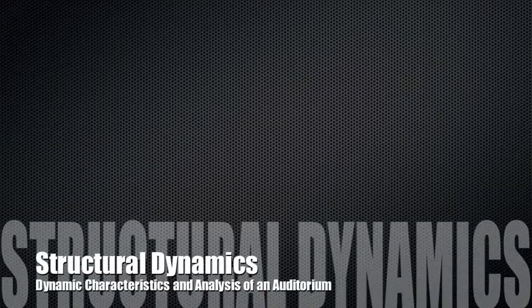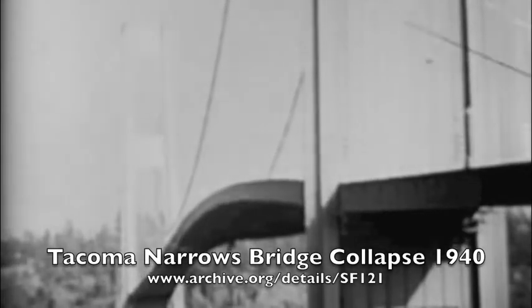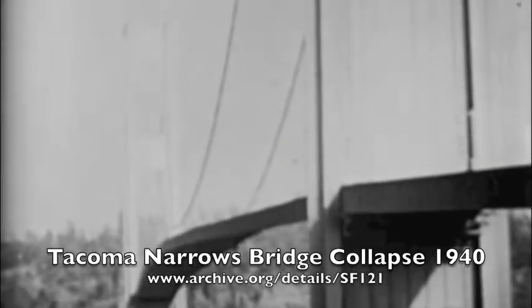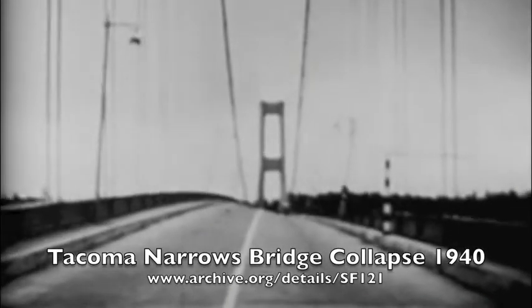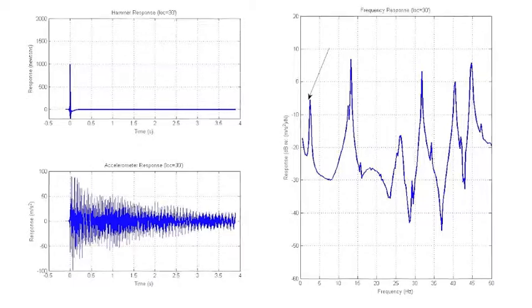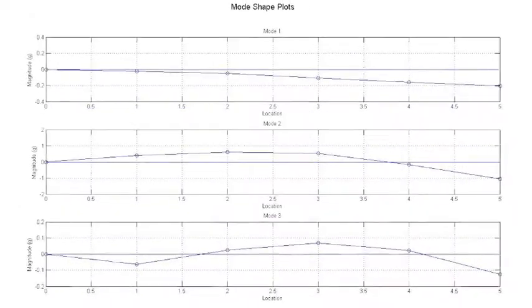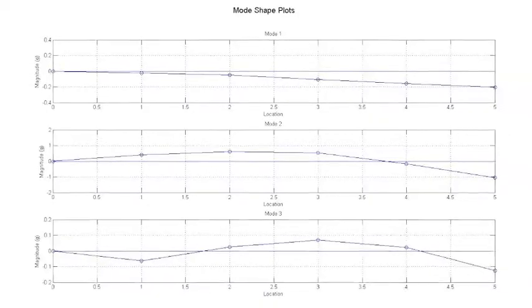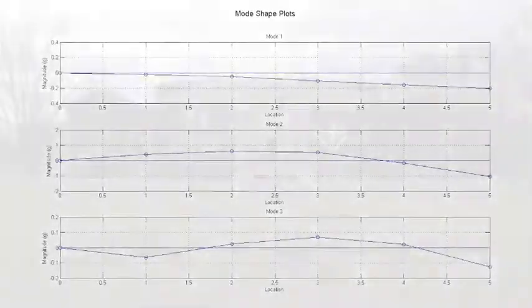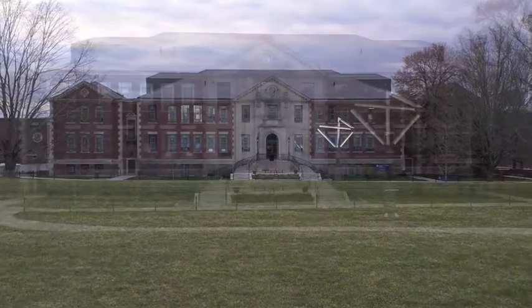Structural dynamics is the study of how a structure responds to an external input, such as a forced excitation or ground motion acceleration. Dynamic parameters, such as modal frequencies and damping constants, are the essential technical information required in engineering analysis and design. Computer modeling alone cannot completely determine the dynamic behavior of structures because of uncertain structural properties, such as damping, nonlinearity, and also boundary conditions.